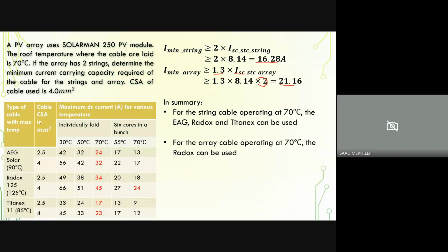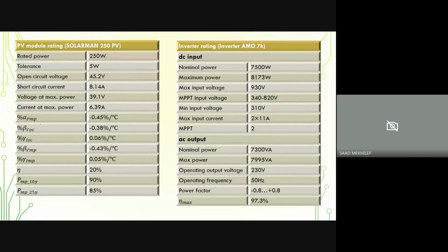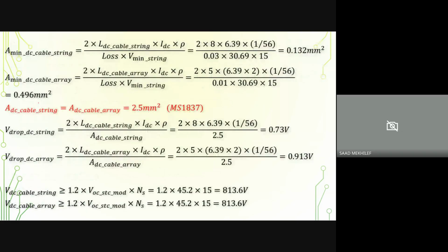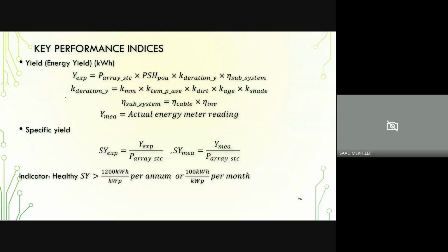All right, what else? This is also balance of the system. In this course we also cover the fuses, for example, the sizes of the fuses, and the bypass diodes in terms of voltage rating times 2 short circuit current. So we calculate the fuse, and then what is the maximum and minimum, and then we have examples.